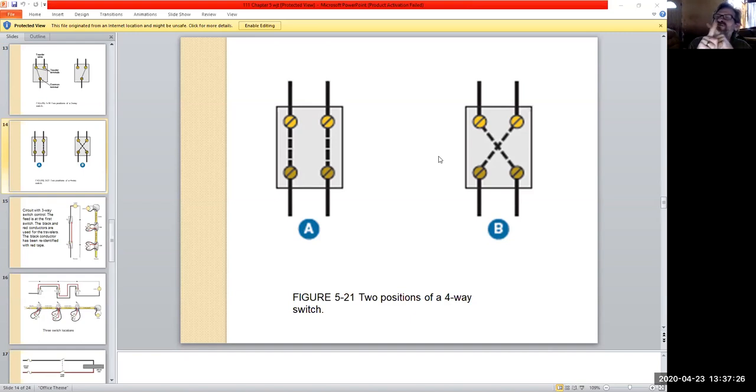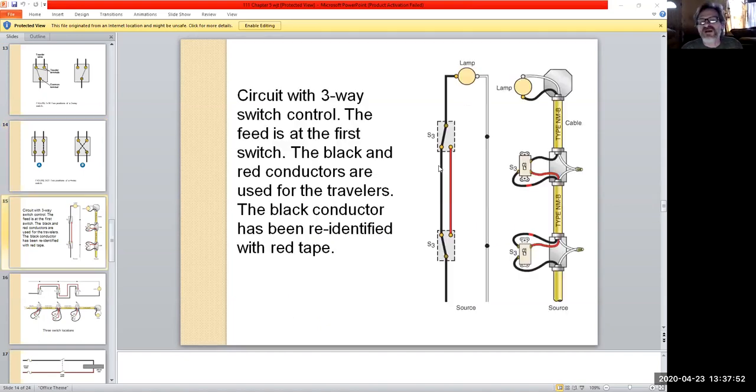So you have to be careful about flip-flopping. If you're using the Romex style sheath, go ahead and use your colored tapes, and that's where the other colors come in handy, like using a red or a blue or something like that to identify these things. That way you can keep your wires consistent when you're running down these things. It's like, okay, wait, the blue goes to this, the red goes to this, and you keep flip-flopping back and forth.